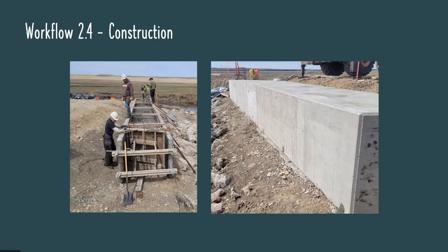And not to go into bridge design itself, but all I'm trying to say is there's a really complex 3D surface. And so it's really nice for us, of course, not to only have that in the 2D document, but to also have that in the construction inspection team's hands and on their survey equipment. And it's a huge success for this project.